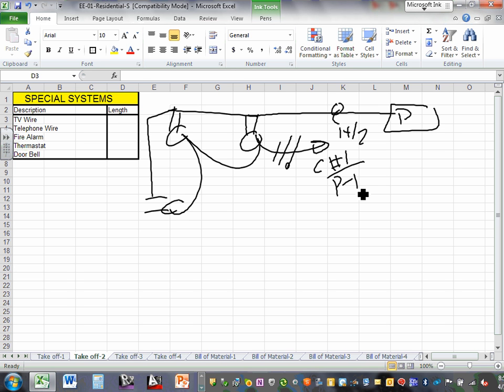The height of these buildings, write yourself, it's 10 feet. The height of this residential project is, you have to write it down, guys, 10 feet. This is a 10-foot building. So when we mount our receptacle, we're going to use for the calculation a 10-foot ceiling. When you go up, you remember you mount it at 12 inches, a foot, count it as mounting at 1 foot. When you go up, then you will go up how much? 9 feet. Now that's where, if it's less than 10, it'll give you a little bit of extra.